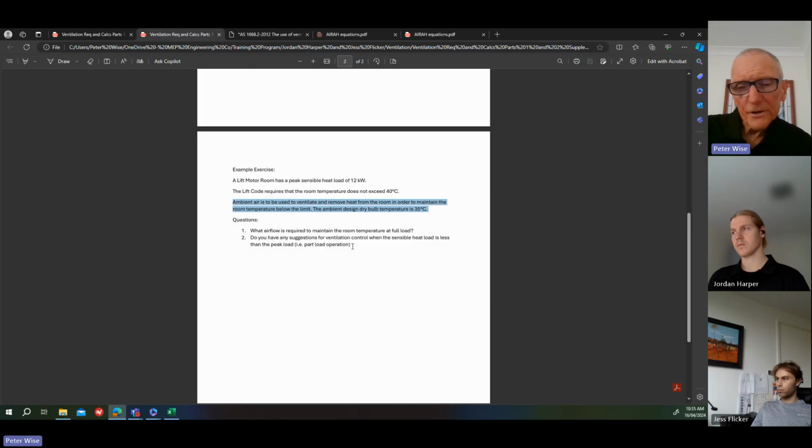So let's say you've got an air-conditioned office space, which is being controlled at 23, 24 degrees, and you've got a storeroom that's got paper in it that they want to maintain at a certain temperature, whatever it may be, then if you've got excess air available, use that air from that space and then discharge it outside somewhere. So the point there is temperature control. You can switch the fan off or reduce the speed of the fan to maintain the temperature in the space. Does that make sense?